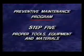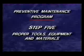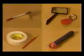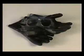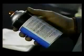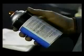Step 5 is utilization of the proper tools, equipment, and materials while performing your corrosion duties. This equipment includes the inspection tools we discussed earlier and safety equipment like goggles and masks that are important for personal protection. Finally, it is important to use the proper abrasives, chemical conversion coatings, and cleaners when treating or preventing corrosion.